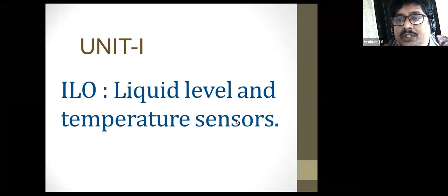That strain is observed by a strain gauge, which is connected to one of the resistors of the Wheatstone bridge. Thereby there will be a change in resistance, so we can get the output voltage, which is the calibrated pressure.